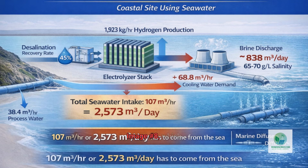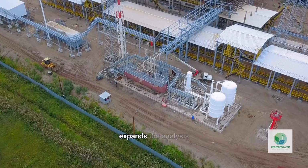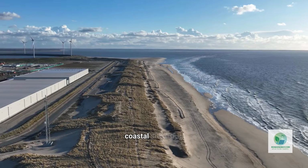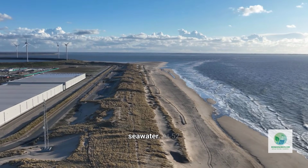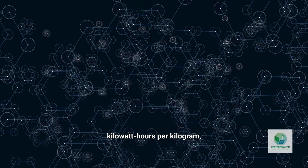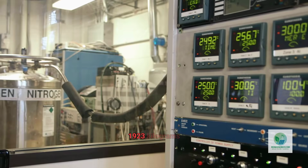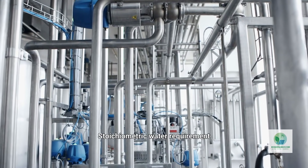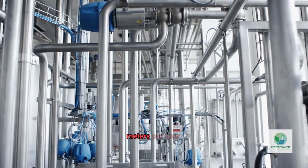Now turn to image number 8, which expands the analysis to a 100 megawatt alkaline plant located on a coastal site using seawater. At 52 kilowatt hours per kilogram, hydrogen production equals 1923 kilograms per hour. Stoichiometric water requirement equals 17.3 cubic meters per hour.